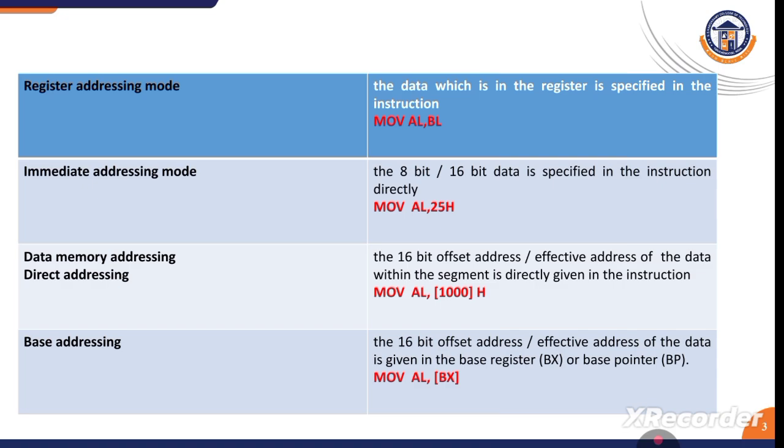Coming to addressing modes, why are they needed? They handle data efficiently, allow accessing memory in different ways, simplify assembly language instructions, reduce program size, and increase the execution speed in the 8086 microprocessor. The classification: immediate, register, memory, base indexing, indexed, and base index with displacement mode.